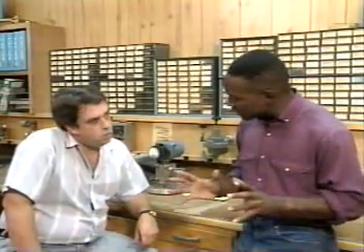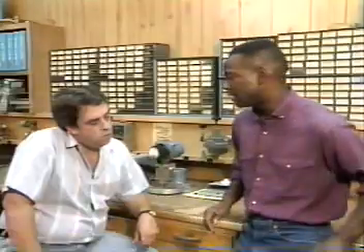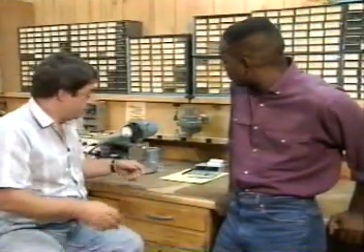Yeah. Now, the level in the number 6 feeder tank is 13.5 feet. Now, if I wanted to know how many gallons were in the tank, how would I calculate it? You'd have to calculate the volume in the tank by taking the formula for the volume of a cylinder and substituting the diameter of the feed tank and the height of the fluid. Then you'd solve the formula and convert the answer to gallons. It's pretty easy to do. Here, let me show you.